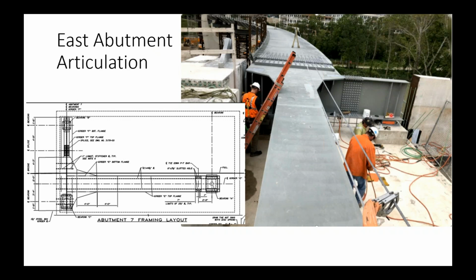These bearings are allowed to slide, which allows us to relieve the stress caused by those temperature strains. And so this abutment has a lot of unique features. And at the end, this entire area is going to be enclosed in a vault and not visible. So we didn't worry too much about the aesthetics of this piece, how it differs from the bridge, but we did spend a lot of time thinking about the behavior and how it will work in the bridge.